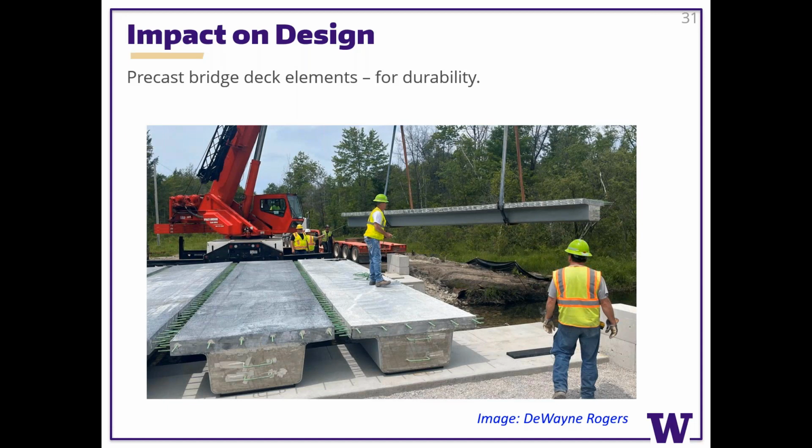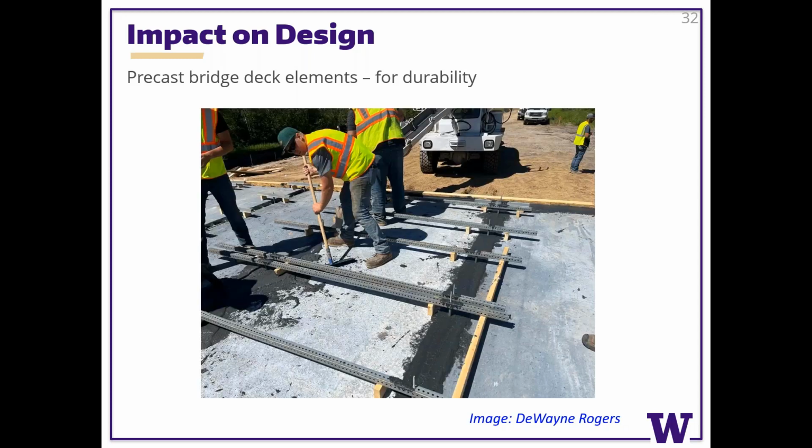And you can see that firstly, they've cast some conventional concrete just in the end here. It only extends in a couple of feet. And that was so they could make some connections between this girder and the adjacent one here. And you'll notice these are the joints, a pretty narrow joint. They only had a 3.5-inch overlap for the bars here. And here they are putting the UHPC joint in.